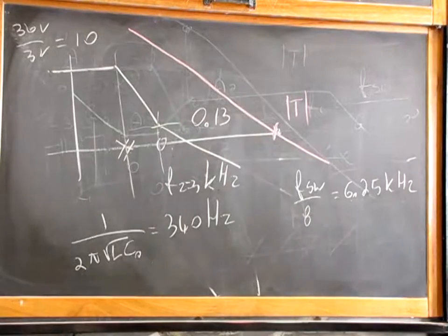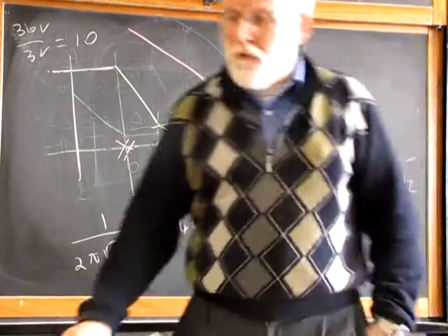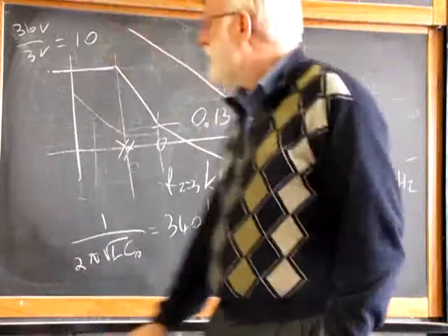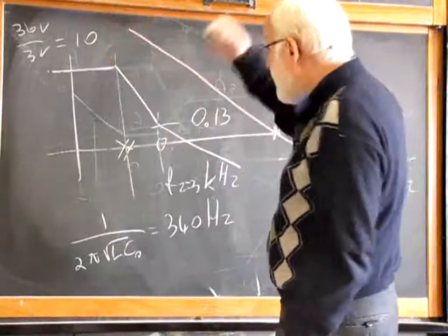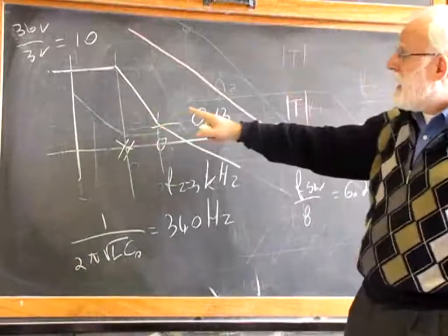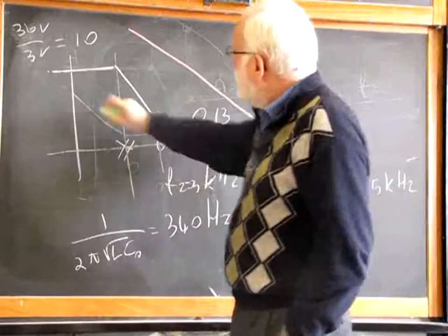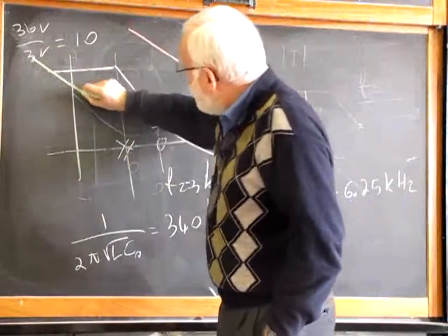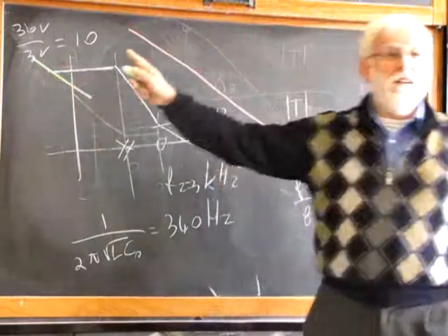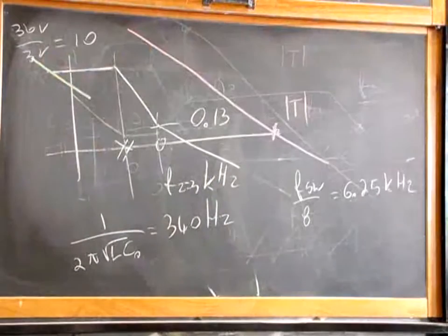So now we need to find out our compensator transfer function. It's not in scale, what I am drawing now. In any case, it has an integration characteristic, so a pole at the origin.